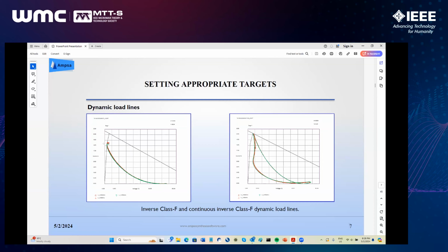So then the knee will mess you around a little bit. So you see here current's at 1.575 or whatever, and there the current will go to 2 amp or whatever. So you pay a price for continuous mode operation, and the inverse class F you pay more current, and the other two you pay with more voltage.